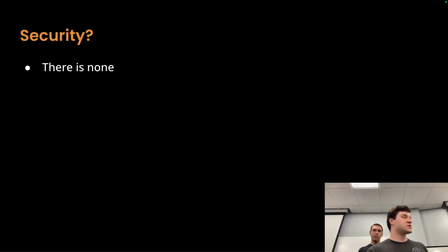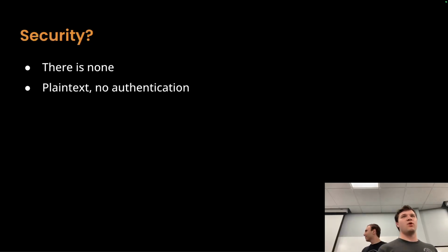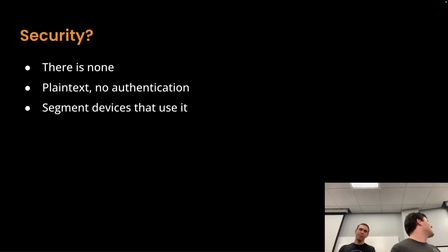So going into the actual security, there is none. It's all plain text. There is no authentication. I mean, it was designed in the 70s. And if you have these devices that use this protocol, just segment them. Don't even think about trying to do stuff with it, other than it being on the industrial side of the house.